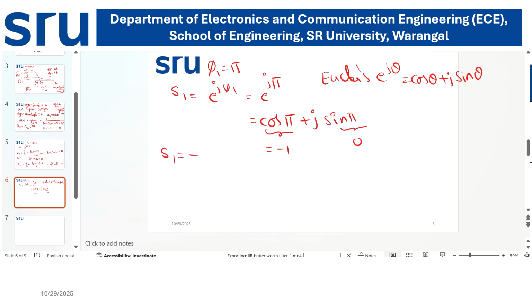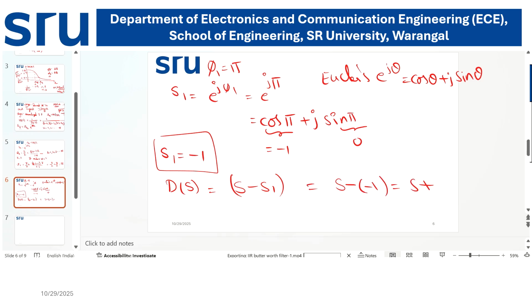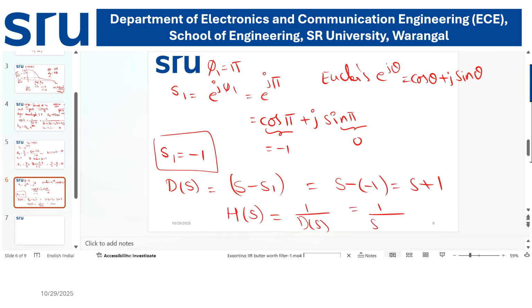Therefore s1 is equal to minus 1. Then the polynomial d of s is s minus s1, only one pole, because the order is only 1. So I have s minus of minus 1, which is s plus 1. If d of s is s plus 1, then the normalized transfer function is 1 by the polynomial, that is 1 by s plus 1.